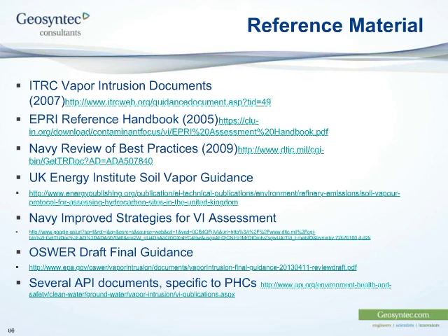Now, we've put a lot of time and effort into the passive soil vapor sampling, where that's a big concern because there's not really a lot of convection or advection or flow, and the rate of transport to the sampler is limited by diffusion through the soil. So we did a bunch of calculations to try to figure out what kind of diffusive supply rate would occur, and then design the passive samplers to have an uptake rate that's lower than the supply rate. And now we get quantitative passive soil vapor sampling, and it works quite well.